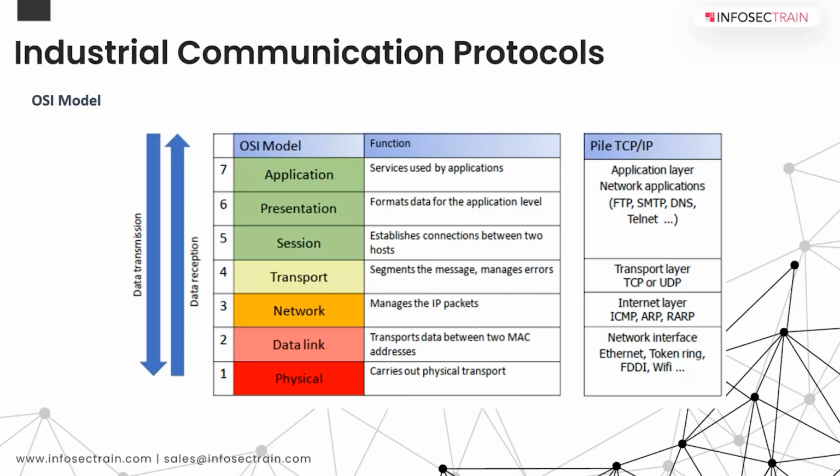If it is oil and gas, petrochemical, or petroleum industry, we follow Modbus, Ethernet IP, and so on, Profibus, Fieldbus, and so on. So in general, in OT systems or industrial control systems, it is first necessary to transmit the data between the sensors and the actuators, right? The Purdue model that you might have seen again and again, between level 0.